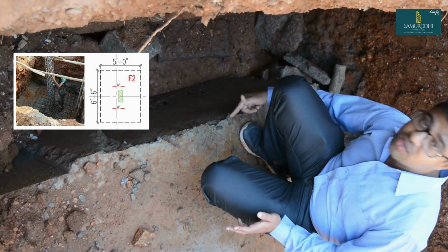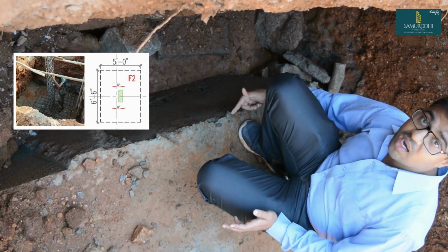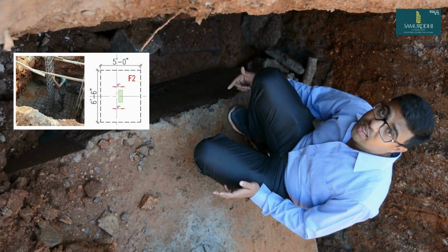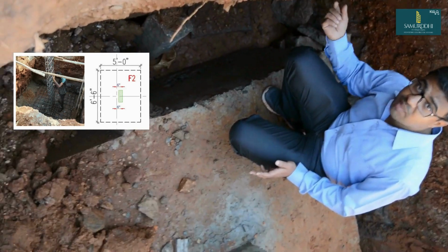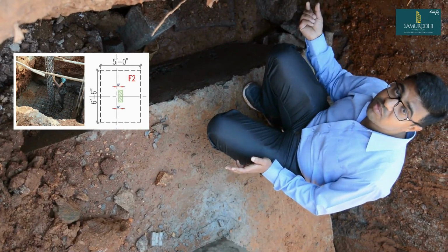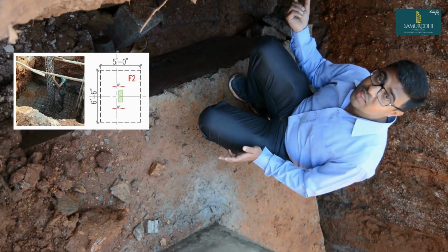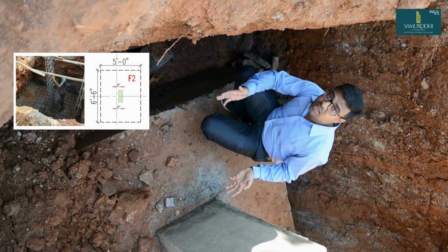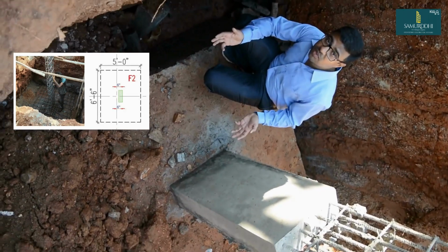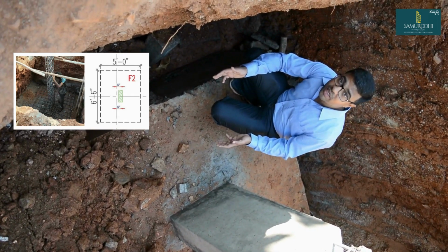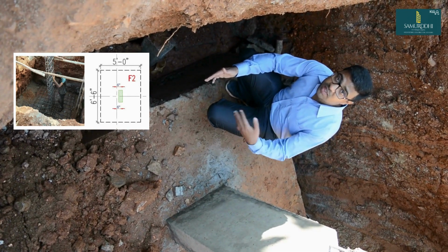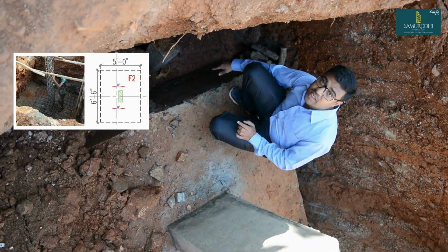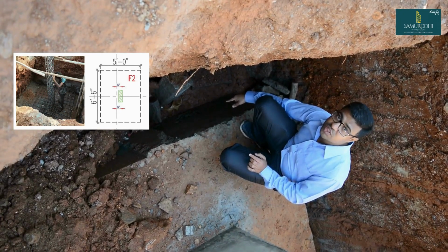In the other foundation the consumption of steel is around 150 kgs, here it could be more than 250 kgs of steel. As for the concrete consumption, there the depth is around 18 inches, whereas here it is 21 inches. The total consumption of steel as well as concrete is more compared to the previous one, which depends on the load that is acting at this point. So accordingly you can see the size.